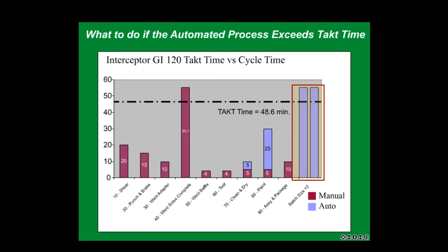While this requires some extra inventory in the cell, most cells start out with so much inventory, and with Lean offering huge improvements in inventory reduction, keeping a few well-placed parts is not an issue. If you can process multiple parts within multiple takt times, you can buffer the next operation and break the constraint.